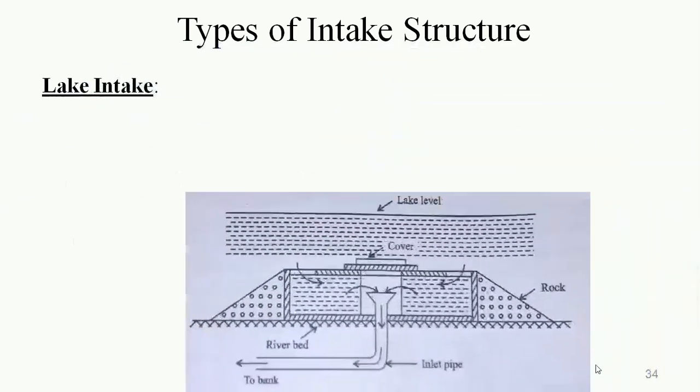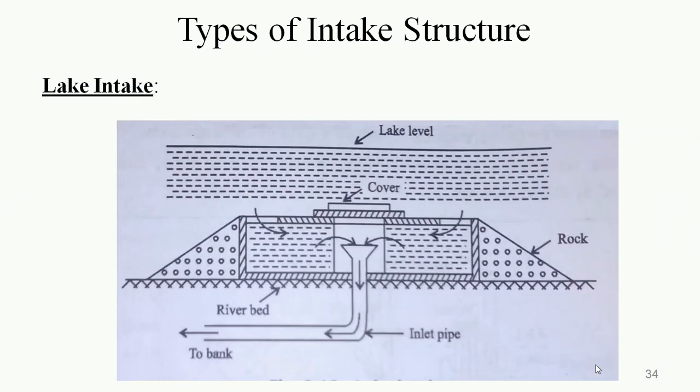The following figure shows a typical submersed type of lake intake structure. The entry of the inlet pipe is bell mouth shaped. At top, a mesh grating cover is provided which prevents the entry of debris. The entire structure is covered with heavy framework to prevent damages against waves.